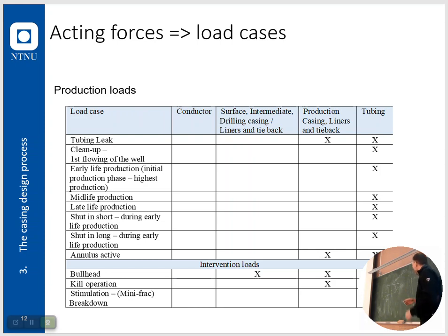You're going from typically 4 degrees on your wellhead if you're subsea. That's at the bottom of the sea always, and you're going up to 100, 145. It gives you quite a lot of thermal stresses, right? And that's part of producing, starting the cleanup.